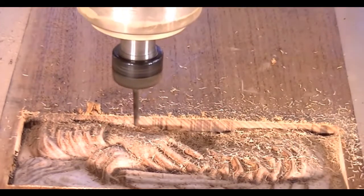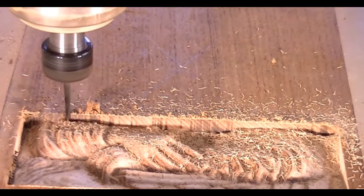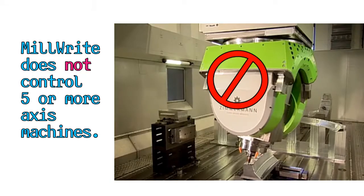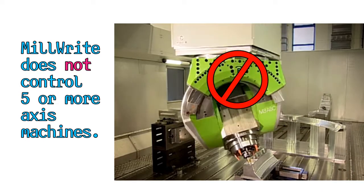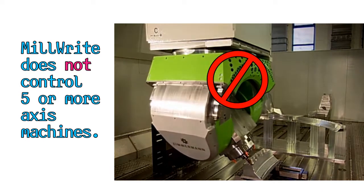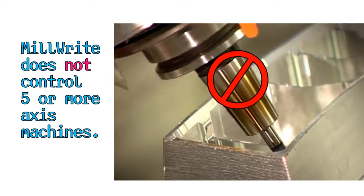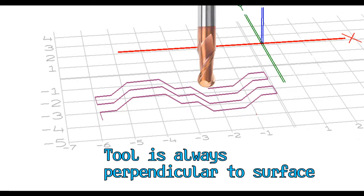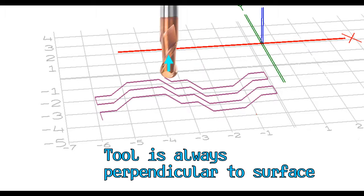MillWrite produces CNC programs that control only three axes, X, Y, and Z, or a rotary axis instead of either X or Y. MillWrite does not produce programs for 5 or more axes that allow the tool to tilt. Therefore, MillWrite assumes the tool is always perpendicular to the surface, and as a result, MillWrite cannot cut a 3D surface grid that has undercuts.